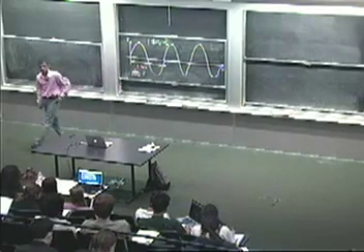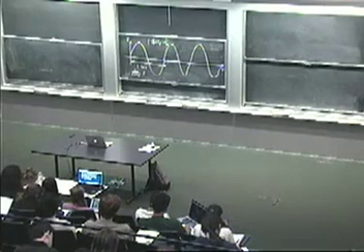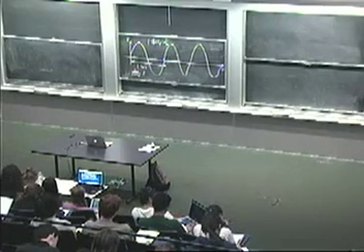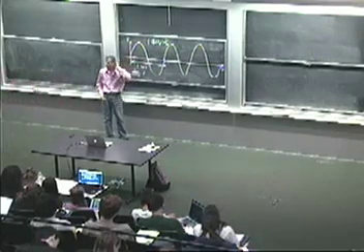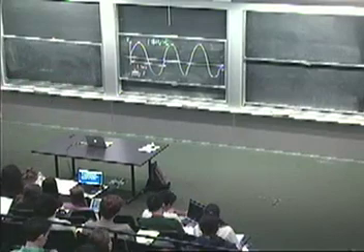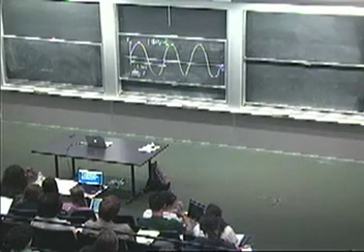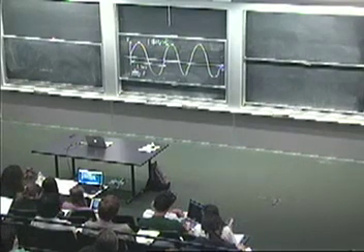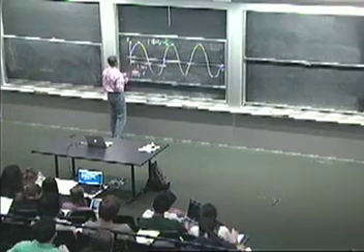Okay. Now, if I sample this at 48,000 or 48 kilohertz, or 48,000 times a second, in one of these periods, how many samples do I get? This is where you have to tell me something. Sorry? 48. Great. So I sample at 48,000 times a second. Each of these things is 1,000th of a second, so I get 48.